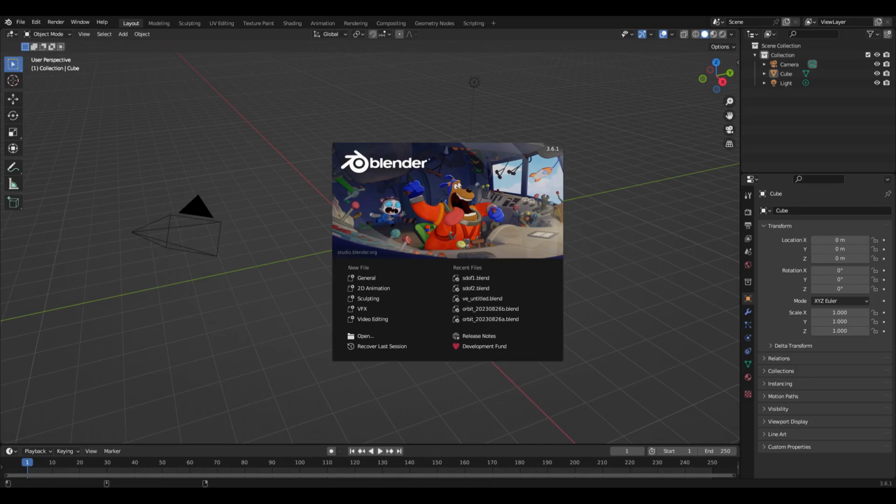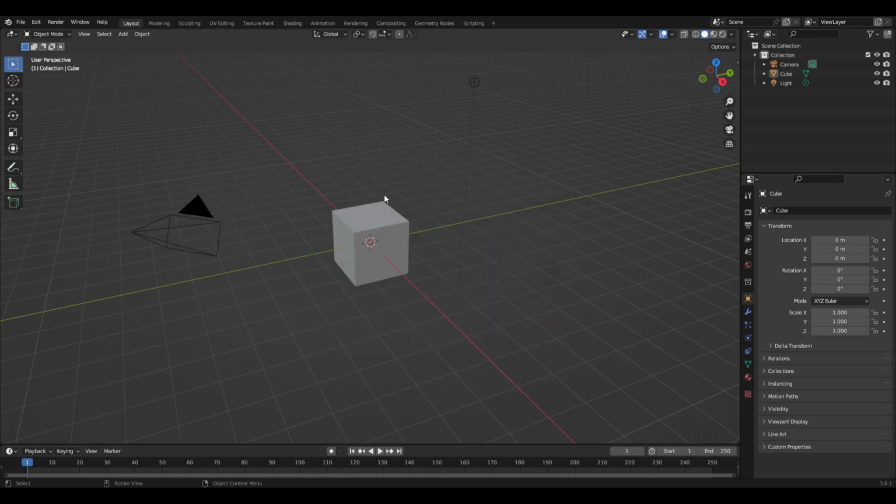Hi, so now I'm redoing some of my previous videos, like this one, the single degree of freedom oscillator, the mass spring damper kind of system. And that's because Blender 3.6 now has a simulation zone, which is a little different way of doing it than what I did before. I was using this ping pong kind of technique. It's kind of a hack in the geometry nodes kind of setup.